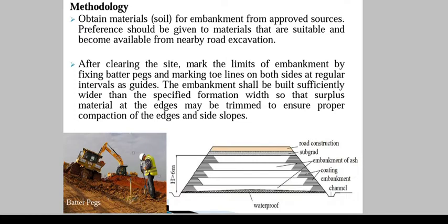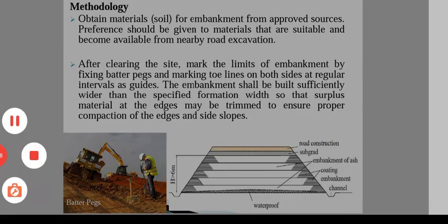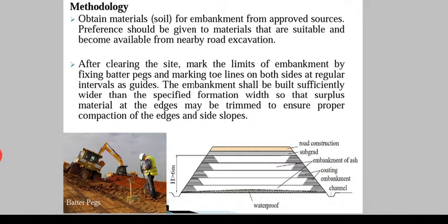specifications mentioned, because whether you're building a state highway, national highway, other district road, or village road, it varies respectively. A minimum of 97% of dry density needs to be achieved as per IRC, the Indian Roads Congress, and the Ministry of Road Transport and Highways, that is MORTH. The specifications are given, and also by the Bureau of Indian Standards. Heavy compaction, modified compaction density is considered.